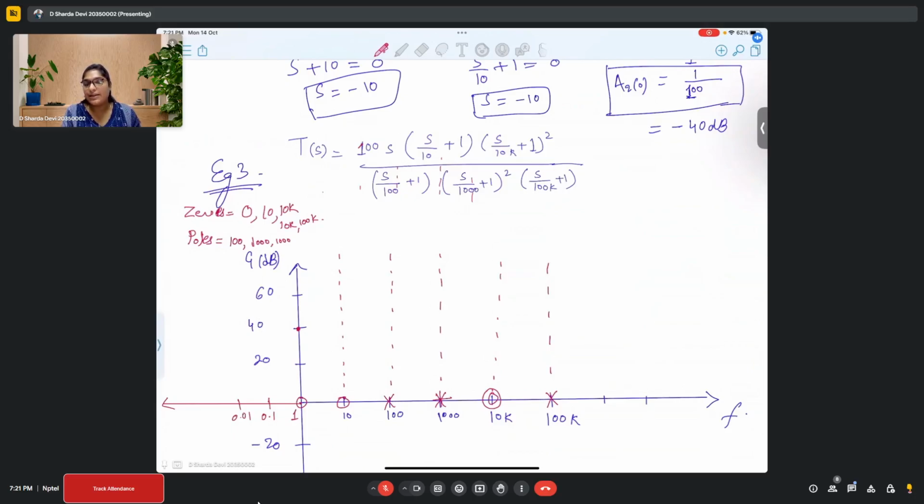There is no chance, right? So for that purpose, and also if I have to talk technically from the Bode plots perspective, we are reducing the plot by a decade. So there is no chance that you can obtain an exact 0 value in this plot, because it is reducing by decades. From that also you can understand it. So that's why we are starting from 40 dBs. Is this clear to everyone? This is something very important.